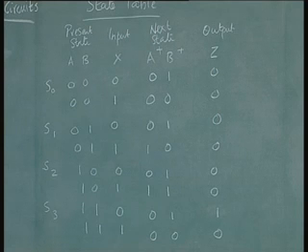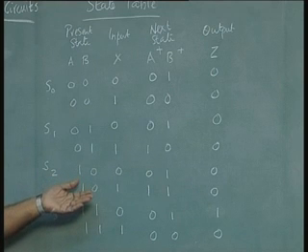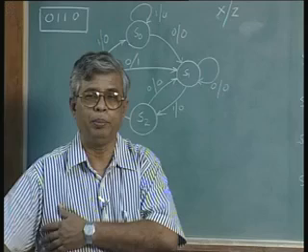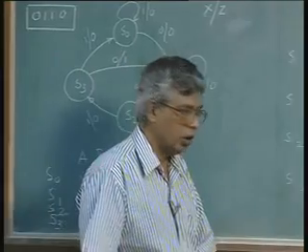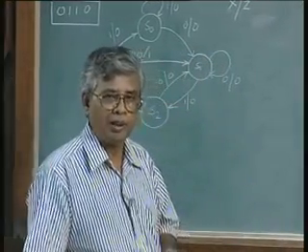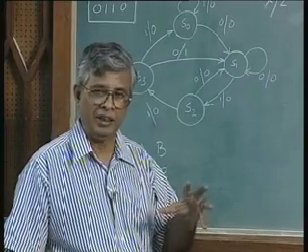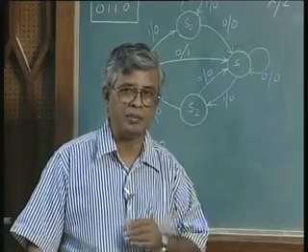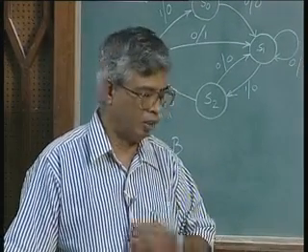And now instead of going through the reduction using Karnaugh maps as we did in the last lecture using gate implementation, I am going to straight away say that I am going to use multiplexers as combinational building blocks. Since we already saw the implementation of combinational logic using multiplexers, we should be able to easily fit in. We know that any combinational logic with the definition of the input output relationship can be implemented using an appropriate number of multiplexers.